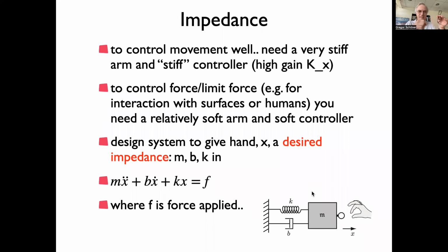And something, a little accident, happens when you get that wrong, right? For instance, with a fragile object like that, I would be not very stiff, so that when there is a mechanical accident, I will not destroy that object by applying too high forces to it. So when it suddenly yields, there will be a limited force along that spring.